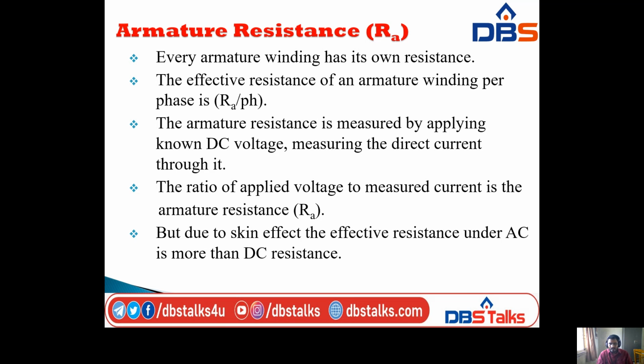So here the armature resistance is measured by applying a known DC voltage and measuring the direct current through it. Okay, next, what is meant by the armature resistance: it is the ratio of applied voltage to measured current. The ratio of applied voltage to measured current is the armature resistance Ra.